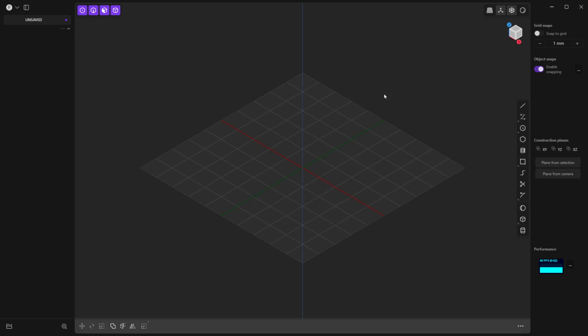Now that we're kind of zoomed in and we're ready to start modeling, we don't have anything on the screen. We deleted our cube and we got our units set, but we don't have any geometry yet. So before we make any geometry, double check in your upper left-hand corner to make sure that all 4 of your selection filters are on. A lot of times by default, you'll come in and the control points will be off and you may see something like this. So hit 5 on your numbers or the tab key to make sure that they're all turned on.